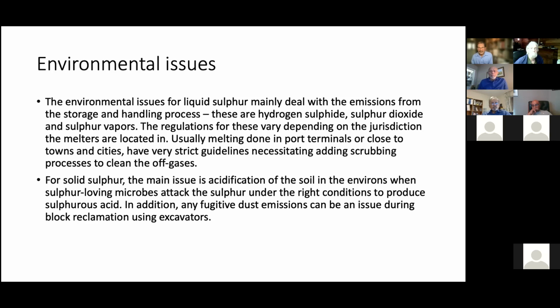Unfortunately, we don't have any regulations for H2S content, liquid sulfur content in North America. It's only left to the individual companies to enforce some guidelines. Everywhere else in the world, there are regulations that you cannot ship sulfur over 10 ppm H2S concentration. Now, a few companies have adopted that guideline, but many haven't. And we transport undegassed sulfur in Alberta and in North America, which is not a very safe thing. People have died trying to open the hatch of rail cars and unloading rail cars. So much for that.